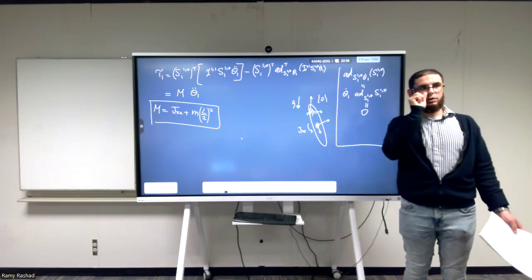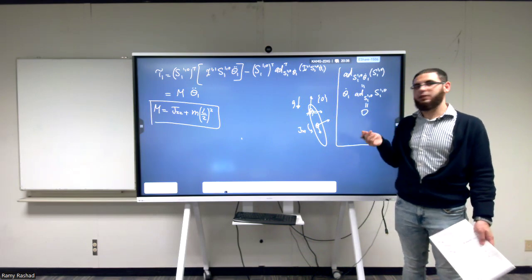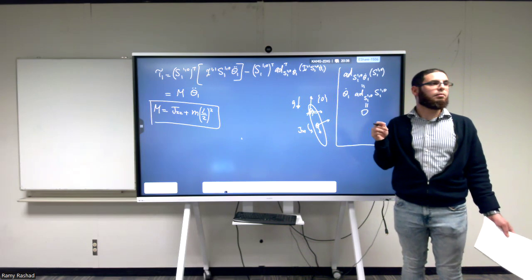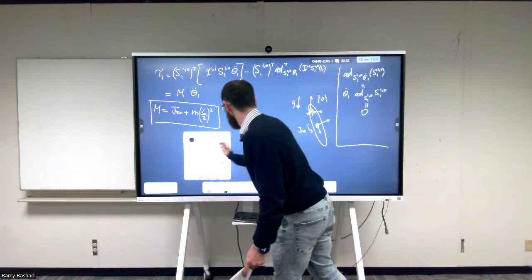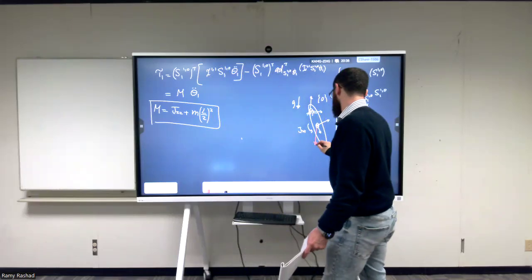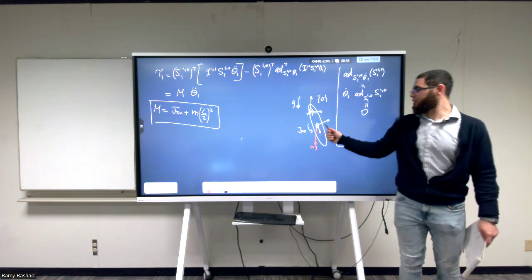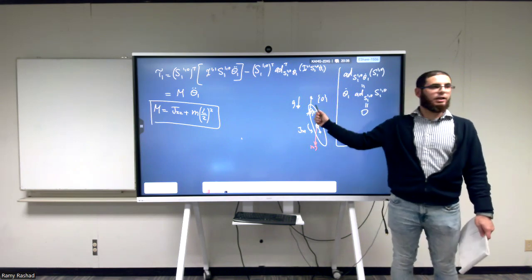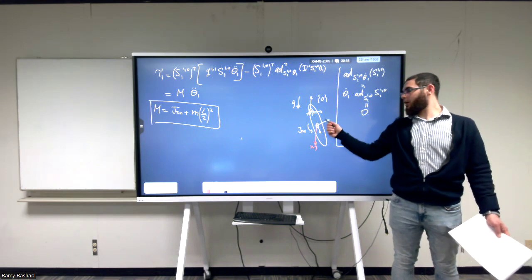What about the gravity force? What does it look like? Where is it applied? At the center of mass. So I have here a force, which I can make into a wrench. I have here a force that's mg. So I can have a wrench applied on the child frame, on the one link, seen in the one frame.